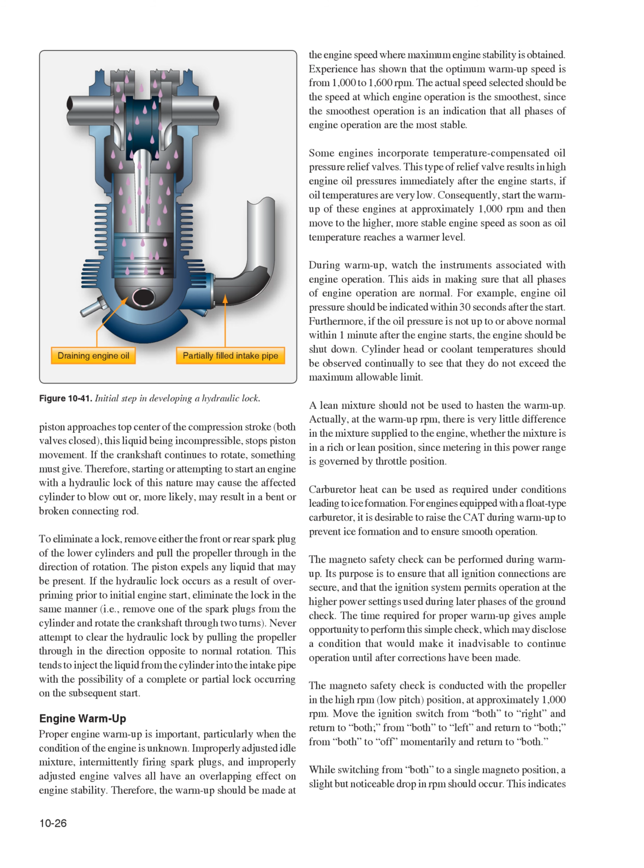Cylinder head or coolant temperatures should be observed continually to see that they do not exceed the maximum allowable limit. A lean mixture should not be used to hasten the warm-up. Actually, at the warm-up RPM, there is very little difference in the mixture supplied to the engine, whether the mixture is in a rich or lean position, since metering in this power range is governed by throttle position.